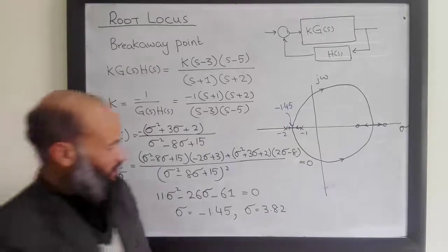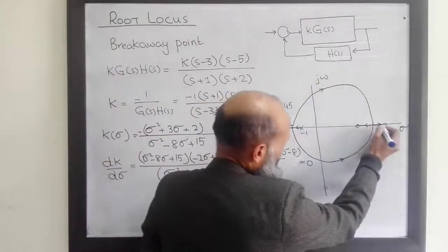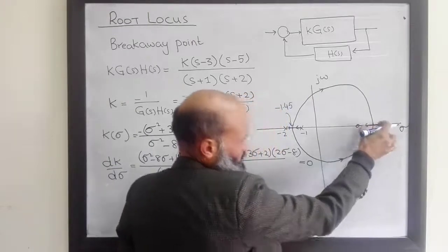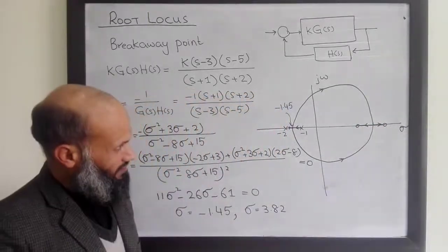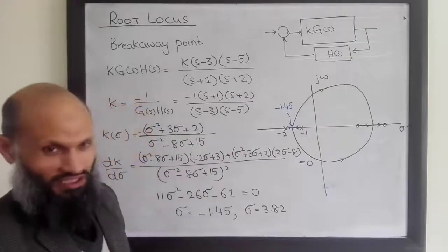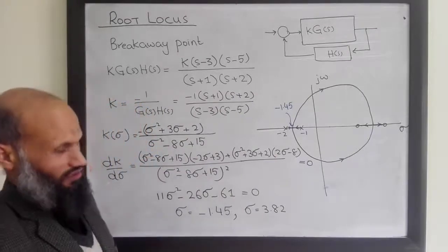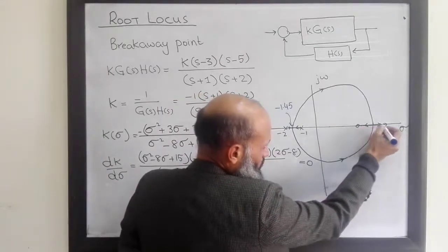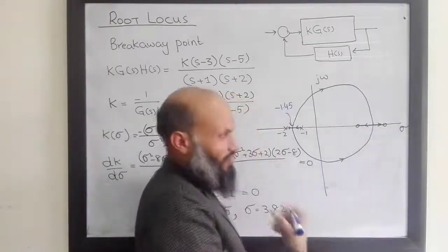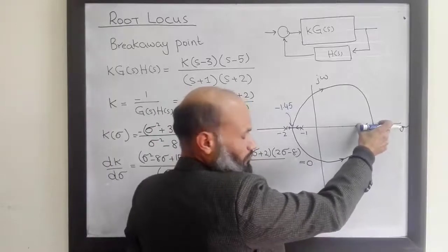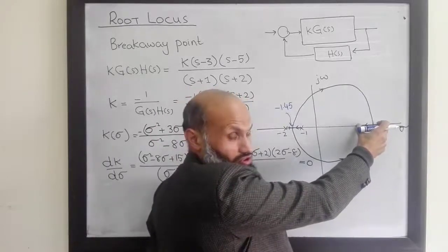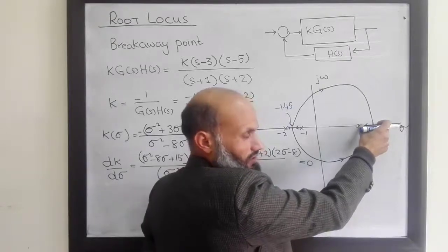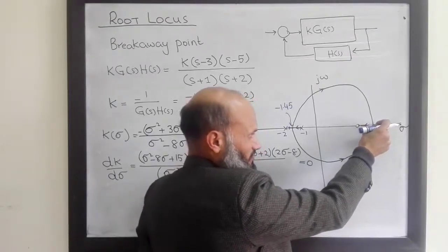If we look at this part of the root locus, among all these points on this real part, which point corresponds to minimum gain? What is the gain corresponding to the closed loop poles at this location? For gain equal to infinity, closed loop poles will approach the zeros. These points correspond to gain less than infinity and even smaller.